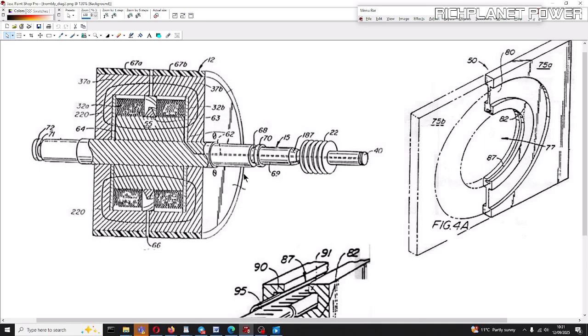So in this machine we don't have the permanent magnets as you have with De Palma's machine and my machine here, right? You have an electromagnet which is outside the disc and the field comes through here, but you still have the same concept because you've got a rotating disc, you've got something which is generating a magnetic field going through the disc which is rotating with it, right? So it's exactly the same principle, co-rotating homopolar generator, but in this case it's got a closed magnetic field path. That's why it's called a closed path co-rotating homopolar generator.